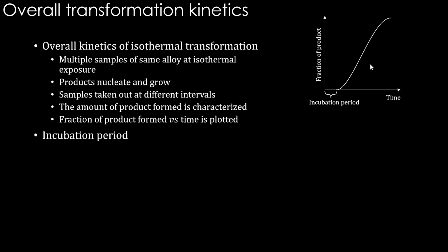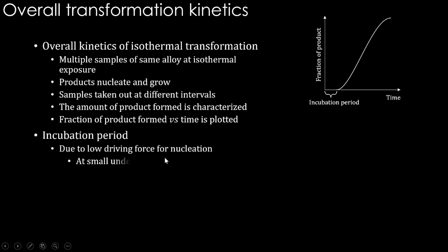This incubation period is there because of a couple of reasons. One is the low driving force for nucleation. You can understand why it happens, because at small undercoolings we know the driving force is going to be less. The delta G bulk is going to be less. You know what we are talking about.